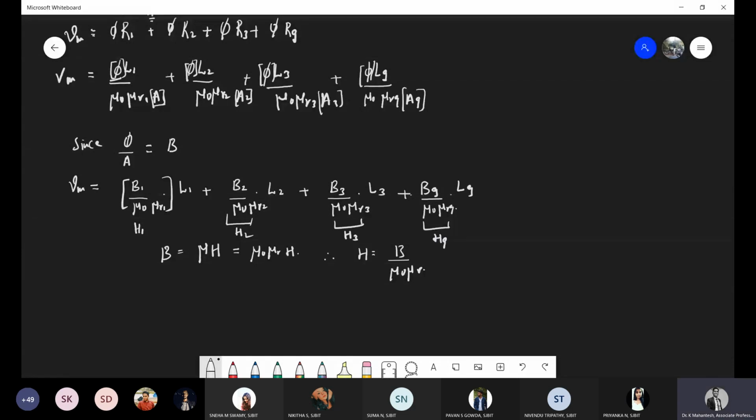So what is my final total MMF equation? The total MMF is equal to Vm is equal to H1 L1 plus H2 L2 plus H3 L3 plus Hg Lg.